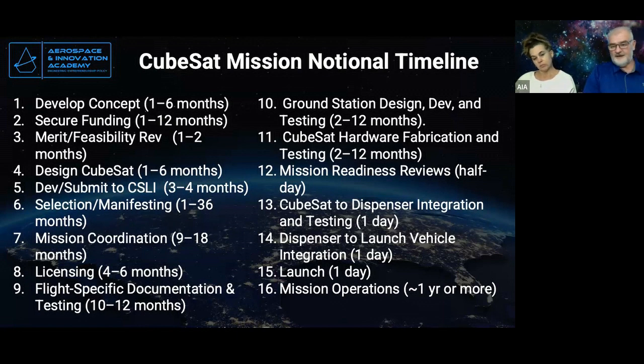All right, often our CubeSats will have deployables, either batteries or solar panels. NASA recommends that you use redundant wires. We literally use monofilament fishing line to hold antennas and solar panels down until you're deployed into space from the P-POD or other deployer.